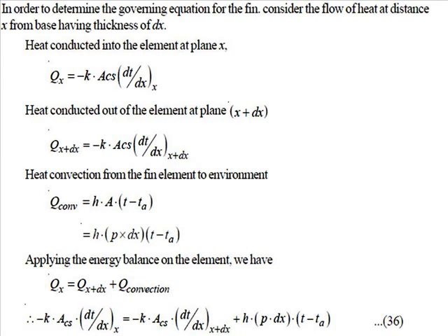For that we are starting with consideration of heat flow at a distance x from the base, having the thickness dx in the positive x direction. So you can say heat conducted in the element at plane x, that is Qx, equals minus kA dT/dx according to Fourier's law, and we'll get Q at x plus dx, at the thickness dx, equals minus kA dT/dx at x plus dx distance.